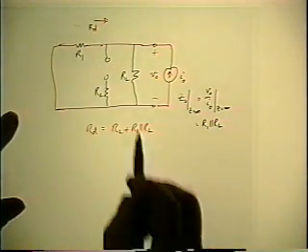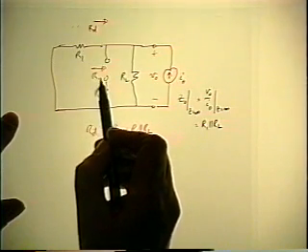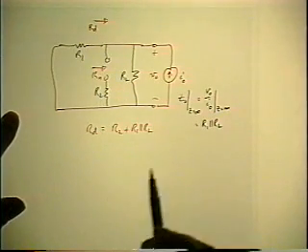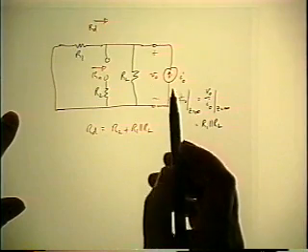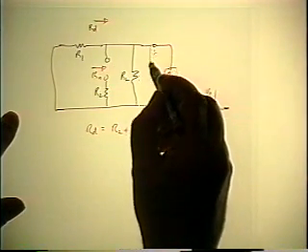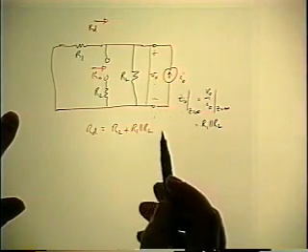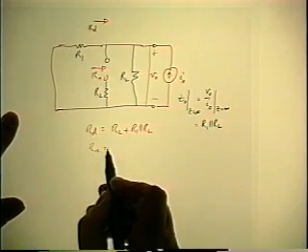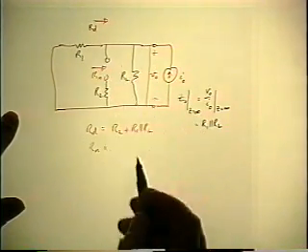Second calculation, apply the independent source and find Rn under conditions that the output is nulled, which is equivalent to shorting the input. The input is the IO. When you short it, the VO is 0. So when you look in now for the Rn, you're going to get only R2, because you've got a short across the rest of it now.